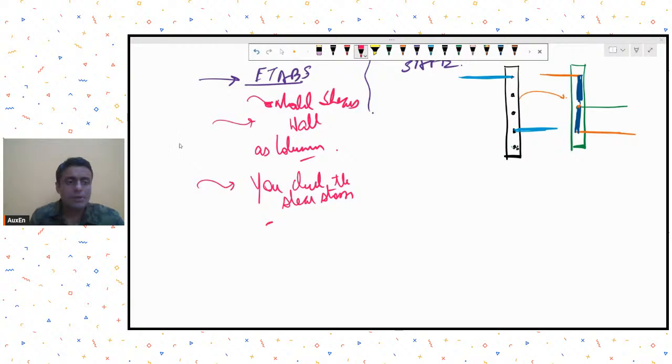I'm not able to quickly recall. Shear forces are shown by V13, V23. But if I want to see the shear stresses, I'm not able to recall, but you can go to SAFE software, go to stresses, and check the shear stresses.